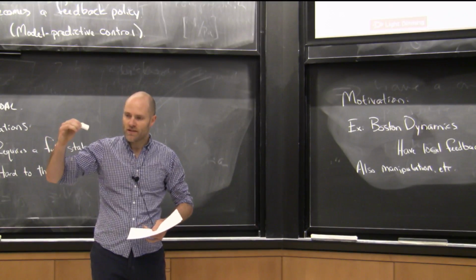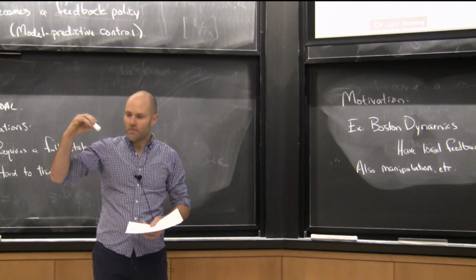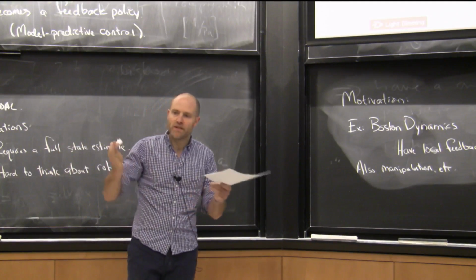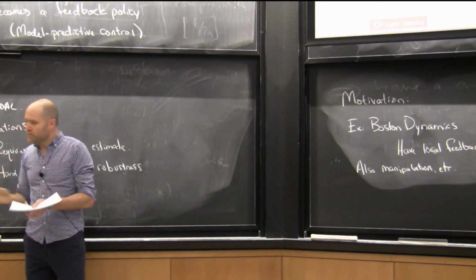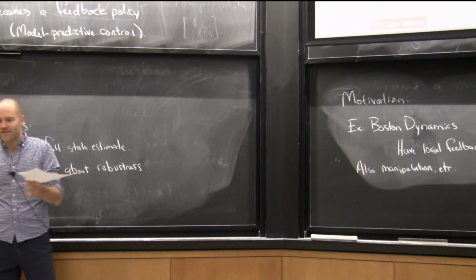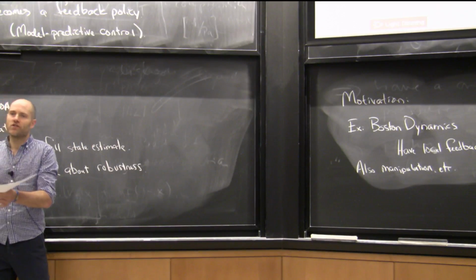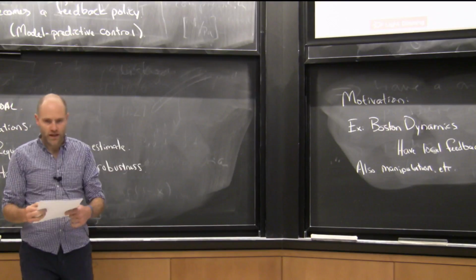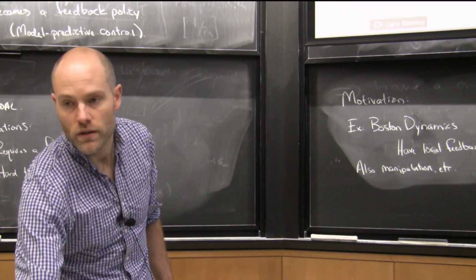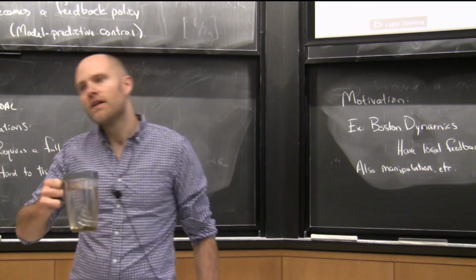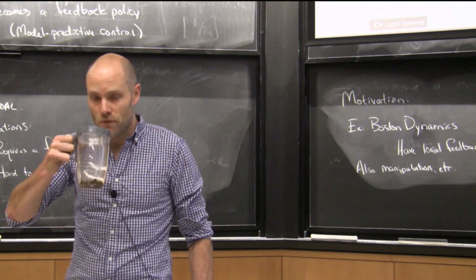And this is a famous classic paper now that was about manipulation, but it was building up this idea of how do I compose not trajectories, but pre-images of if I were to take this set of actions for some amount of time, it's going to work for a large set of initial conditions, for regions, okay? But somehow we lost that in the trajectory world, where trajectory optimization works well and randomized motion planning works well. And so how do we get it back and do feedback motion planning?